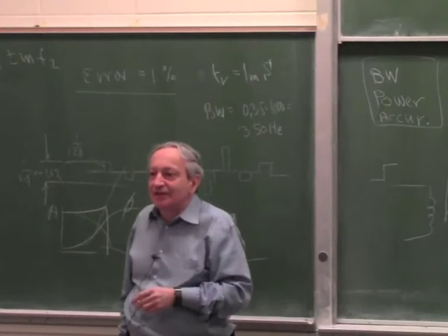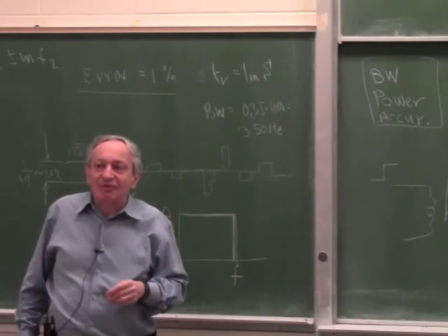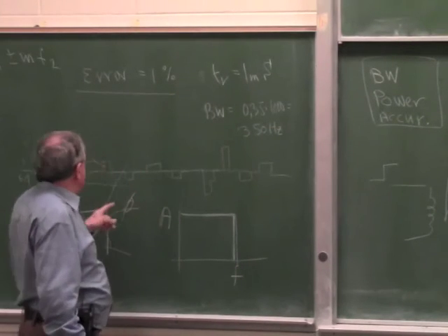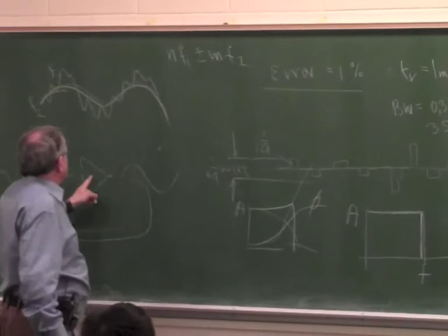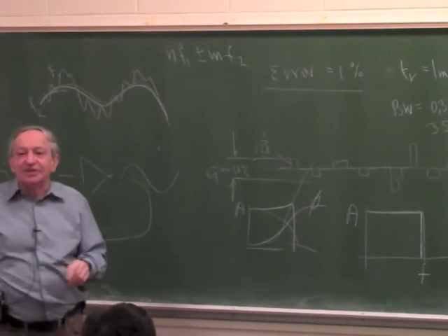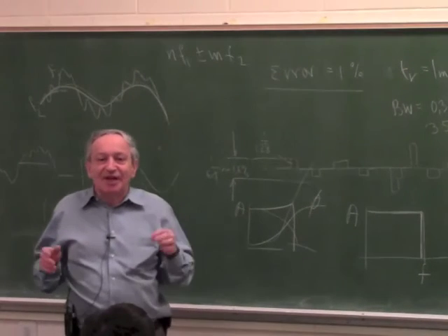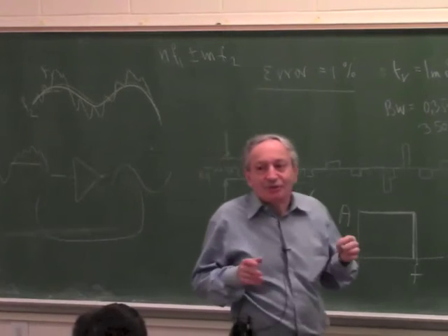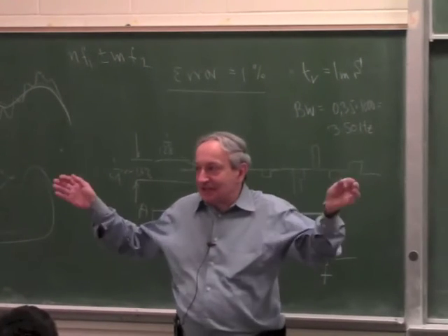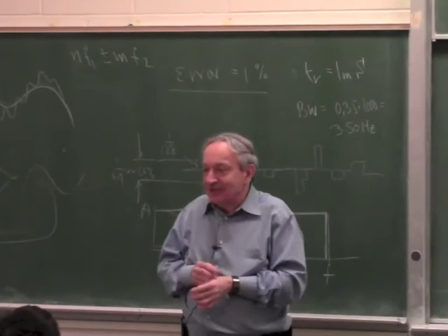Yes? You don't want noise? Yes, because the amplifier is made of stages typically, and maybe the first stages will be able to amplify the high frequency and generate a lot of noise. Because the higher the frequency, the less you want to amplify it, because it radiates like electromagnetic waves, like noise.